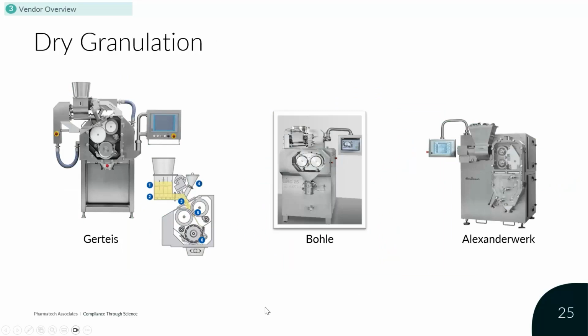Let's look now into dry granulation. In many of today's continuous rigs, you can find implementations of dry granulation processes already. It is, I think, a common technology, in particular when it comes to a certain range of APIs, let's say 5 to 30%. If you have more, let's say, melt granulation, of course, then this is not so much considered. But dry granulation is one of the main routes today on continuous manufacturing rigs.